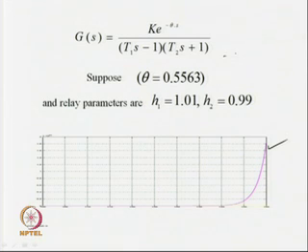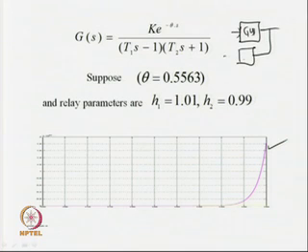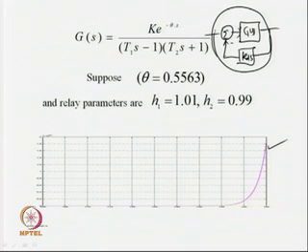One way of overcoming this limitation is that you have to stabilize the unstable open loop process. So, how can unstable open loop processes be stabilized? Given an unstable process of the form G(s), if I provide some inner feedback controller K_D(s), or rate controller, in the inner feedback path, then this overall dynamics is such that it provides stabilization to the open loop unstable process. With this, it is possible to change or increase the value of theta, that we shall discuss later on or in some other lecture.